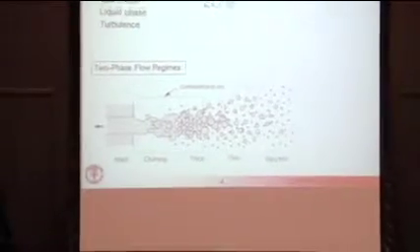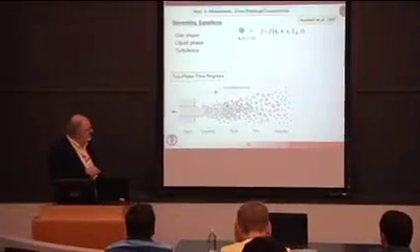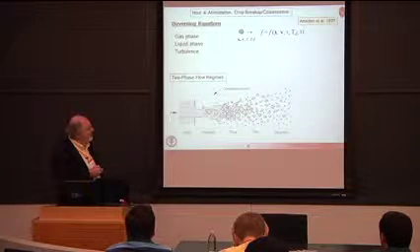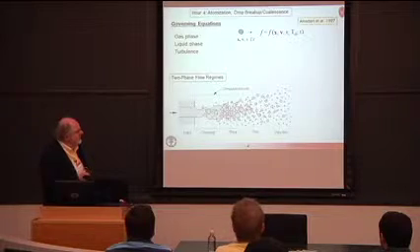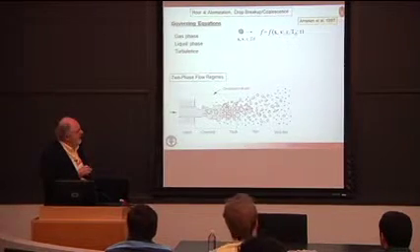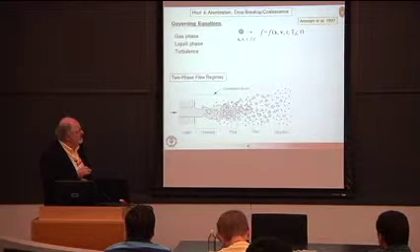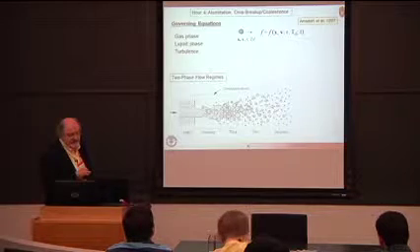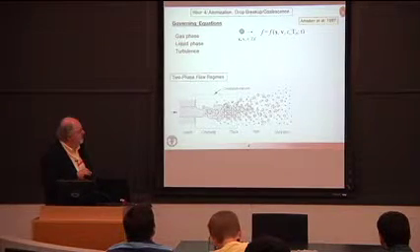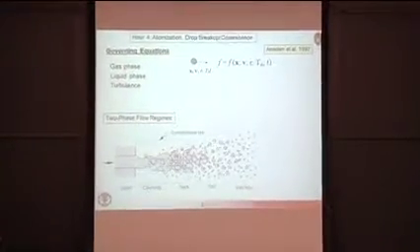So if you think about describing a spray, we have this collection of droplets here. It's very useful to think of a droplet distribution function, which is a function of position in the spray. It describes the distribution of velocities of the spray droplets, the size range of the droplets. You could add other parameters such as the temperature of the droplets. And of course, this distribution function would change with time.